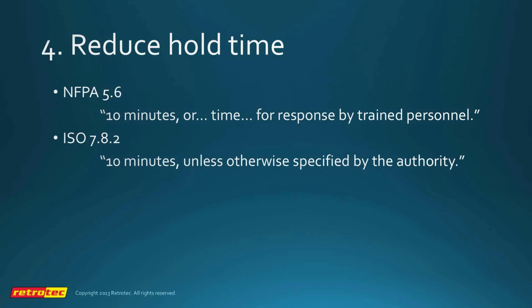So both standards say that the retention time, or the hold time, shall be 10 minutes, or a time required for response by trained personnel. ISO says unless otherwise specified by the authority. The authority usually doesn't know about it, doesn't know to specify it one way or the other, but this is something that can be thought about in the design phase. It's usually not.